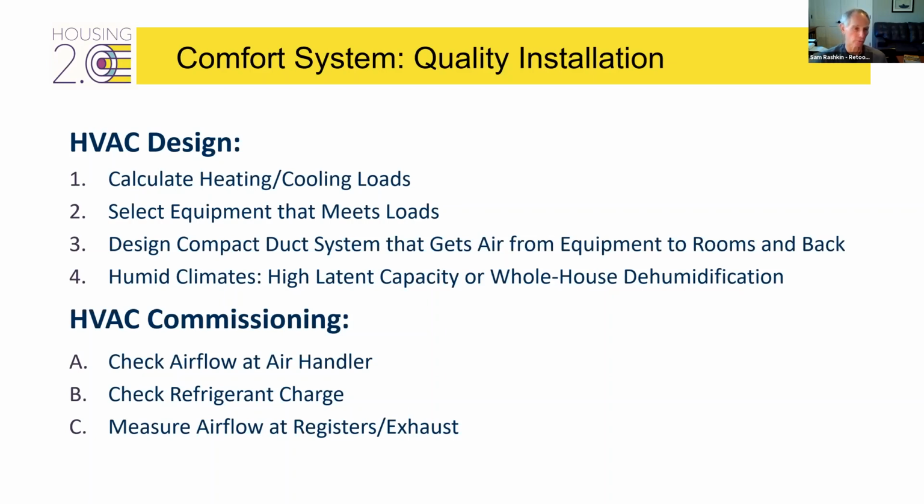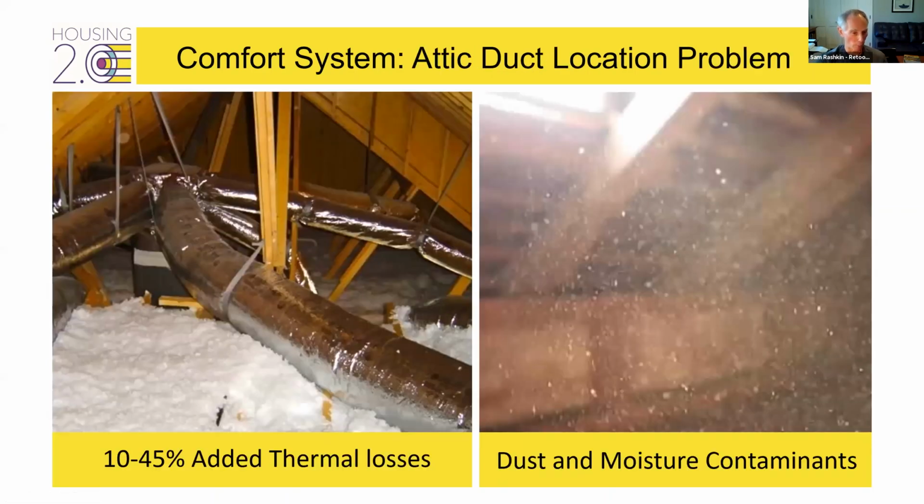And what's critical is all the commissioning: checking airflow, checking charge, and measuring airflow at all the registers, even the exhaust fans and the ventilation ducts. All that should be measured to make sure we have comfort throughout the house. One more point I'll reemphasize is the comfort system in the attic is insanity to me.